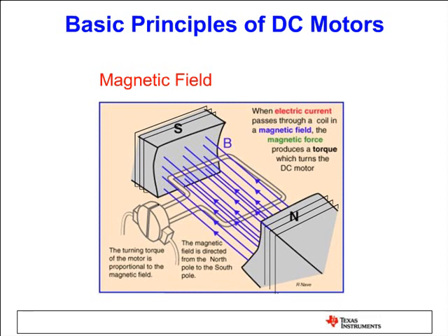That's very important, because we need to remember all these features while we talk about FOC, because FOC, vector control or field control, is nothing but imitation of DC motor control. So we keep this theta field constant during the whole operation.